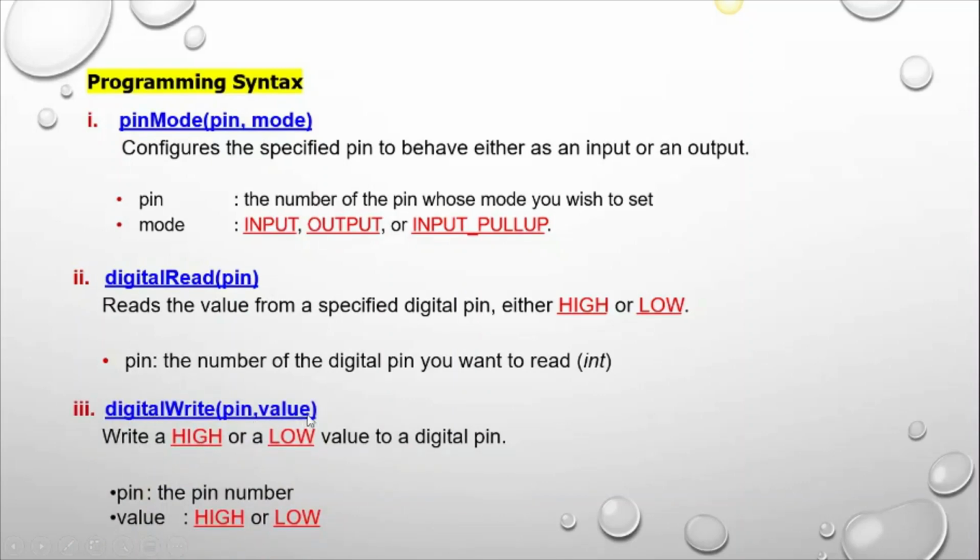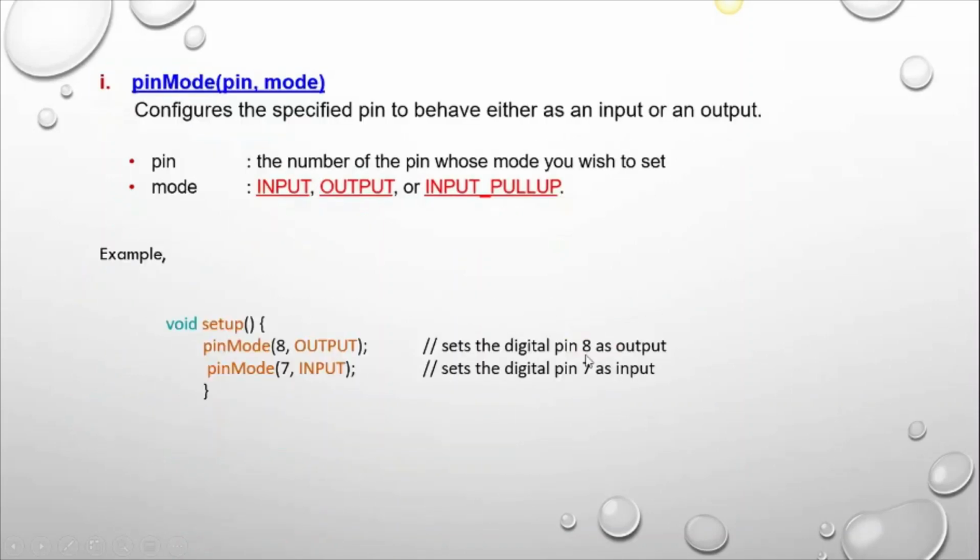So in the digital write pin value, you can write a high or low value to that digital pin. So pin is the pin number, value either high or low. Okay, now we look into the example.